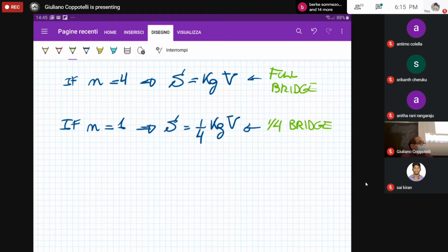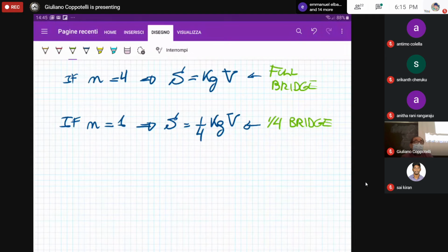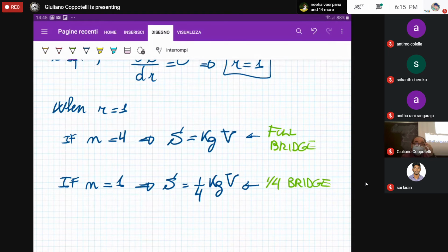There is a current flowing to the strain gauge, and therefore the whole measuring circuit could melt, just because we are exceeding the maximum voltage, the one corresponding to the maximum power that the measuring circuit could dissipate because of the heat, because of the Joule effect. So these values of the sensitivity are the good ones without any information concerning the maximum dissipating power, okay? So it is the maximum that we have.